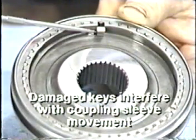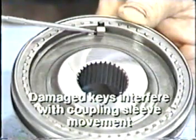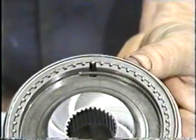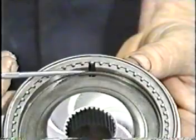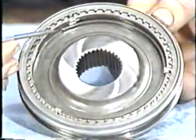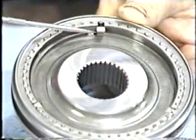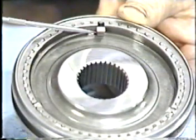Improperly installed or damaged insert keys can interfere with coupling sleeve movement, causing hard-to-shift, locked-in gear, or won't-shift problems. It can also create uneven pressure on the synchronizer ring, which then fails to adequately grip the drive gear, causing gear clash when shifting. The insert keys are held in place by the retainer springs. Installing the springs in the wrong direction, or in some transmission models, such as the M5R2, installing opposing springs in the same direction can create shifting problems. Springs should also be inspected for proper tension.